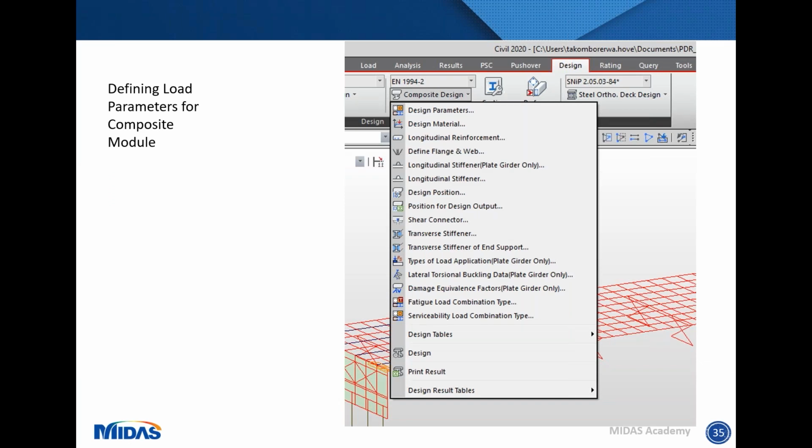So as I discussed earlier on, you can just work your way through the software, and you define different parameters, similar to what I mentioned for the steel design. And as you work your way down the menu, you have the option to add all different types of properties. So you add in your design materials. Again, for the steel, sometimes if you're using thicker steel sections, you might specify a yield stress of 345 or 335 if you're using something over 60 mil thick.